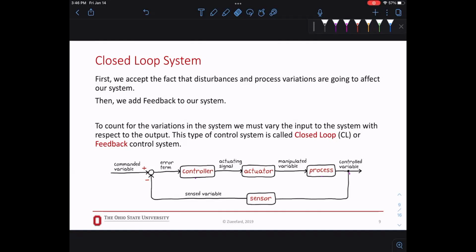So if you had a sensor, you will have some sort of noise, but sometimes in our practice to learn things, we're going to put a simple line. That's still a feedback. It just means 100% of everything went. So we have the perfect sensor, all right? You get that sensed variable, compare with the commanded variable, and feed the error to the controller, right?